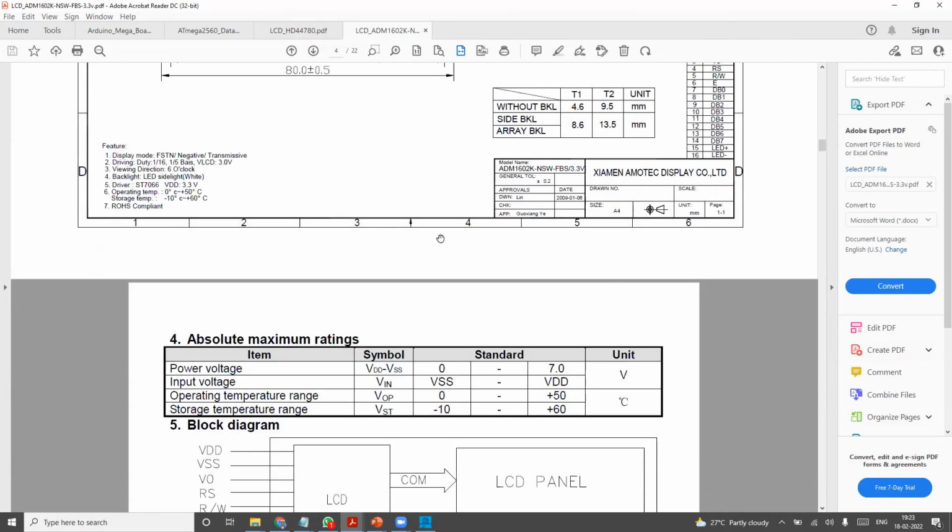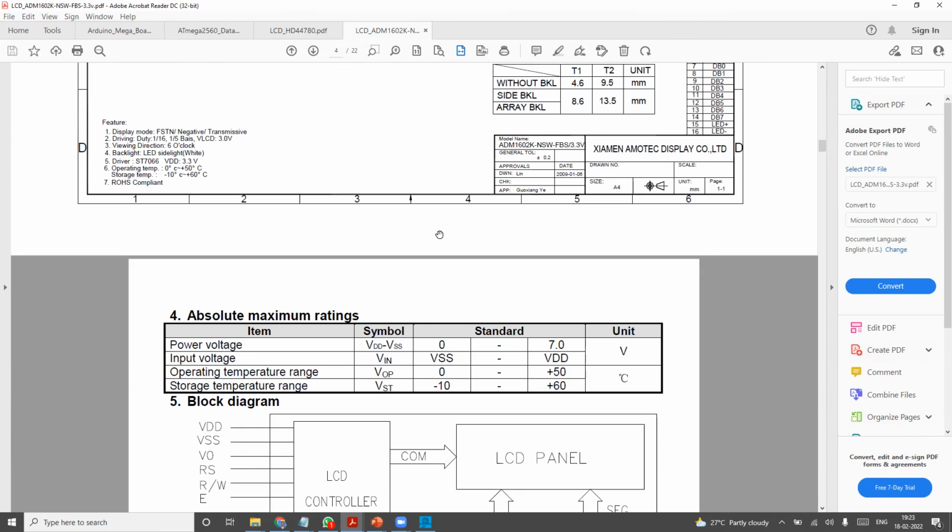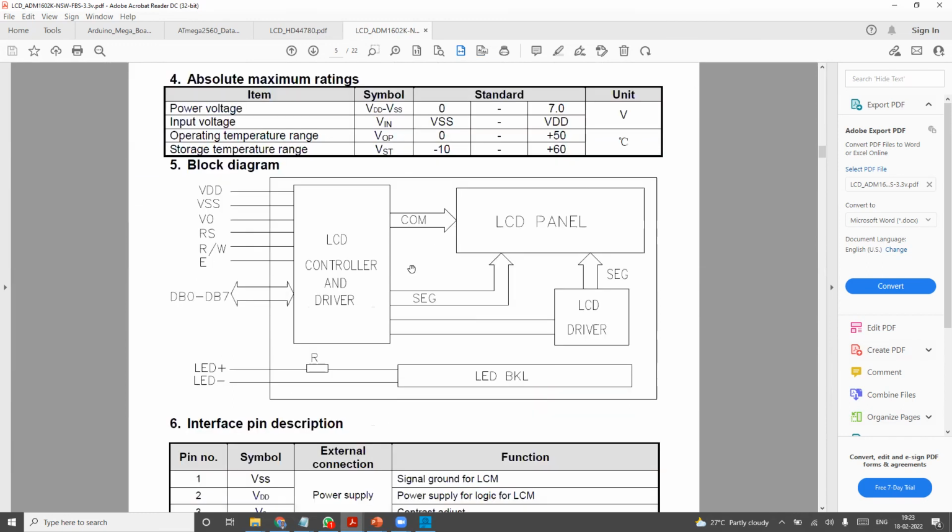These are all there in our data sheets folder in our Google Drive. I've shared all of them. Now, as I told you, see here, there is an LCD controller. This is your interface. DB0 to DB7, and enable. And there's one more thing called read or write. You're going to read the register or write. We are going to discuss write. That's why I didn't talk about read.